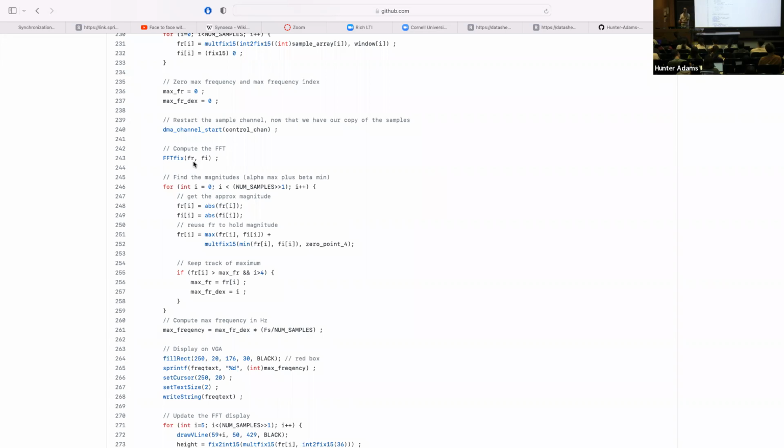And if either core reports that it's in the chirp pause state, which is to say the state of silence between chirps, and furthermore, it reports that it will remain in that state for as long as it takes to gather a batch of ADC samples, then that core is eligible to detect a cricket. Because you can be absolutely confident that the batch of samples that you gather will not include any chirp data from core 0. If it reports otherwise, then that core is ineligible to detect a cricket, because if you detect a cricket in that batch of samples, it's entirely possible that it was generated by that core.